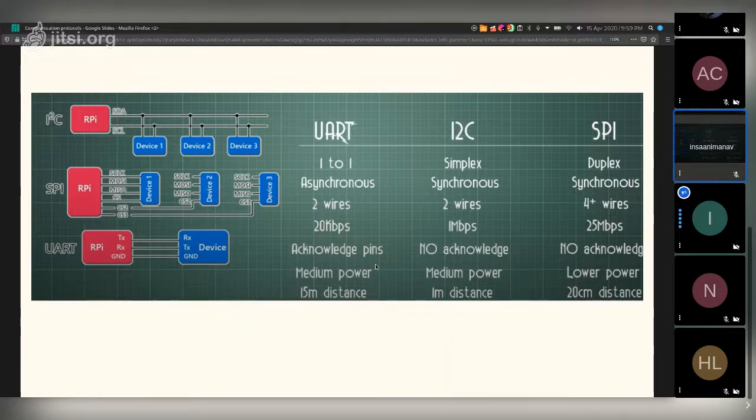As far as I can remember, this is what the implementation looks like: if the microcontroller on the other side sets the acknowledgement to high, that means it's cleared for data transmission and it can send data back to me. So it could be like the classic RS-232 protocol. Similar to RS-232, yes: request to send, clear to send, ring indicator, data terminal ready kind of things. Exactly, in which you have framing error and all. I guess you all are talking about that topic only.